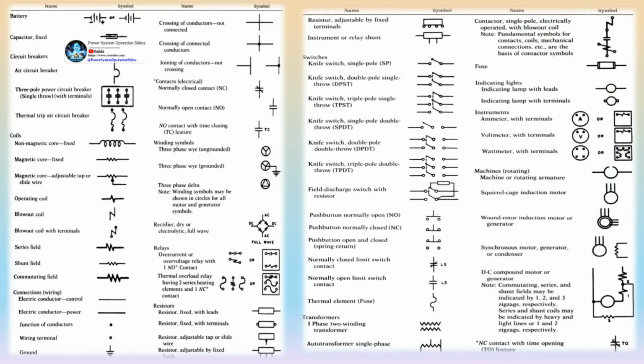It is sent to another substation called a distribution substation, where it is stepped down to 11 kV and then from 11 kV to 440 volts. Industrial consumers are supplied electricity at 11 kV and residential consumers at 440 volts or 220 volts.